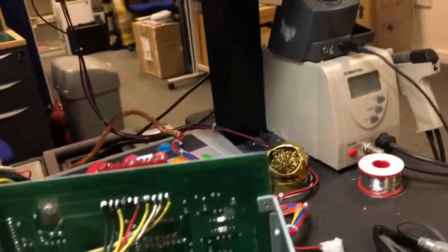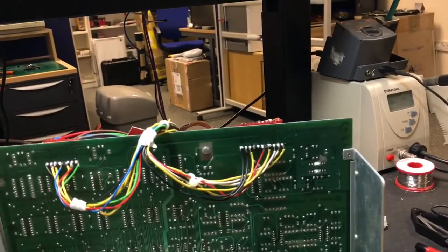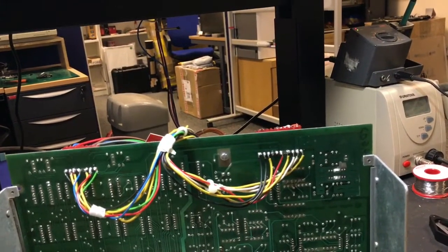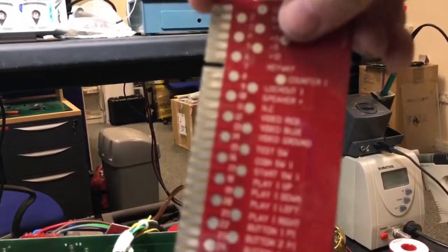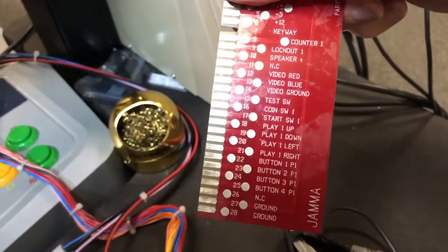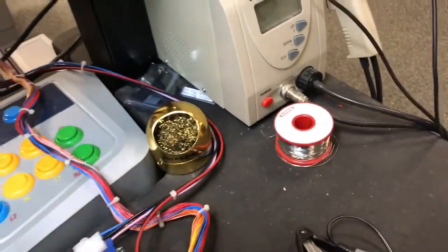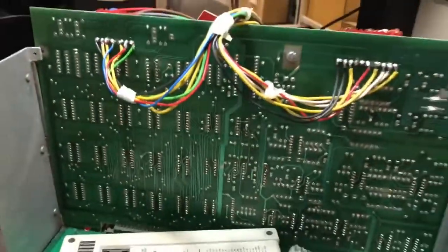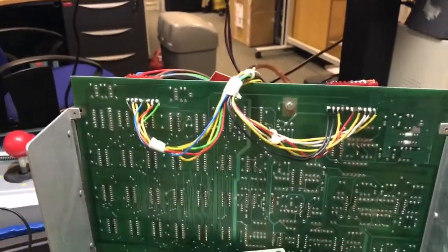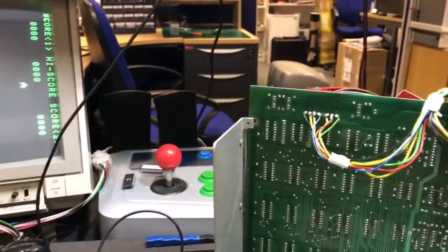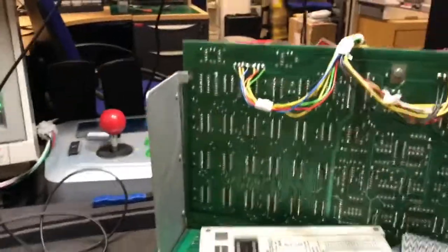Okay, so on a little bit further investigation, what I find out is actually I've only got start SW1 hooked up on there, not coin SW1. The green one there is actually pin 17. Pin 17 on the jammer rig is start SW1, so I didn't wire up coin, so I will do. I'm going to wire up coin now from that to wherever it goes on one of these two connectors, and then make sure that I mean, I can actually just ground it out. That would, yeah, let's see if we can just ground it and make it work.